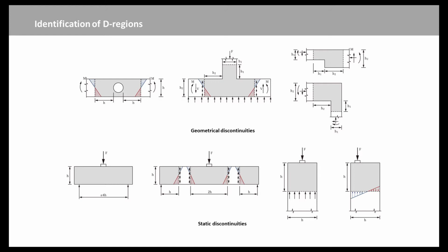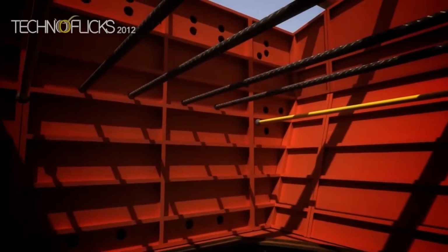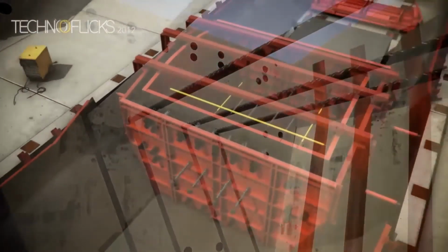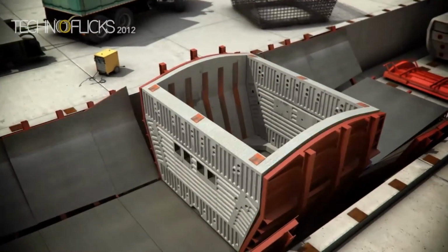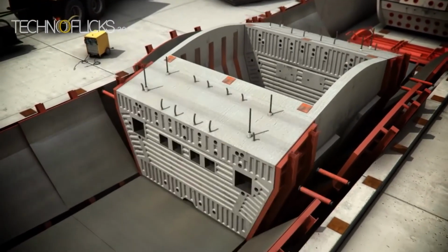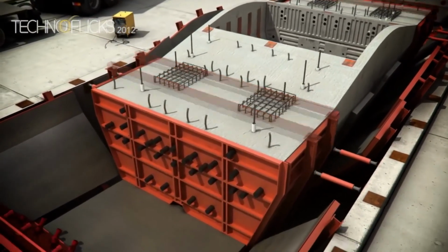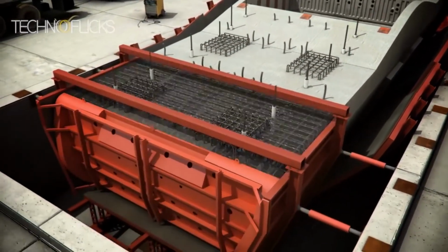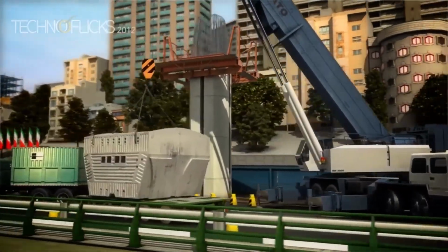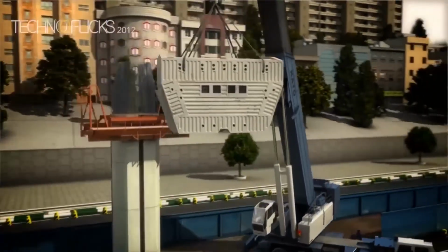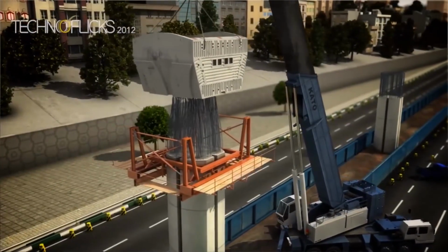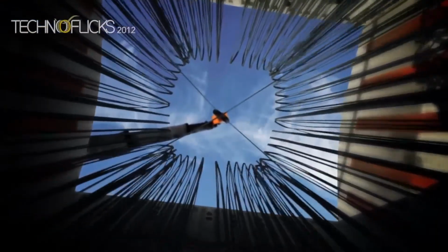Strut and tie models are helpful tools to design the necessary reinforcement, which helps to arrange the transfer of loads through the D regions towards the B regions. A suitable truss model has to be identified for the design calculation. However, in order to find a solution which meets the serviceability limit state requirements, avoiding excessive crack width, the chosen truss system should be as much as possible in agreement with the real stress state situation according to linear elasticity theory, and the lower bound theorem for plastic methods.